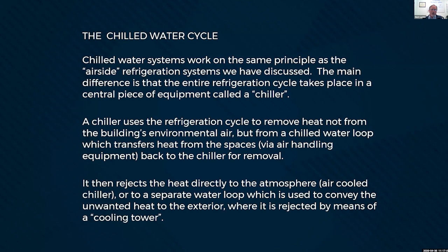Then basically the chiller will reject the heat into the atmosphere if it's an air-cooled chiller, or into a separate water loop, which conveys the unwanted heat to the exterior by means of a cooling tower.